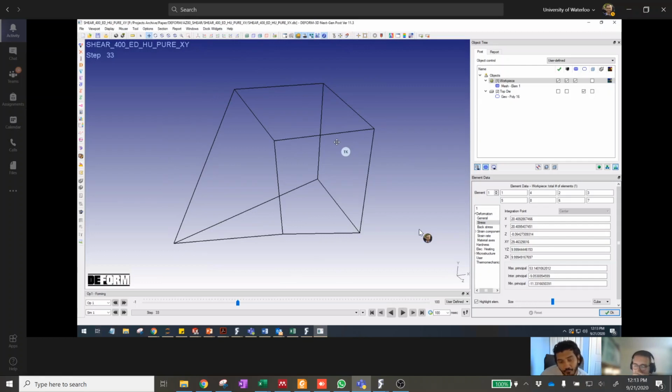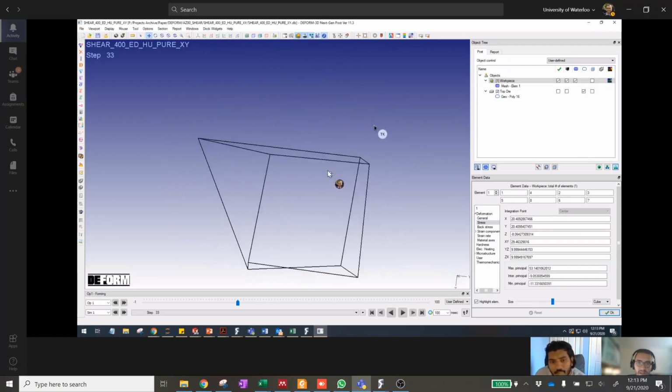The ones that you had previous to this. Boundary conditions. Velocity boundary conditions. What happens if you remove the z? Yeah, that might be the problem, that there's a z constraint here when you apply those boundary conditions. It's not allowing contraction in this direction. It should contract in the Z direction.